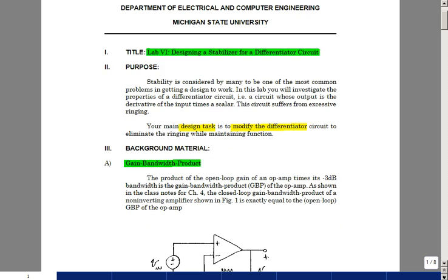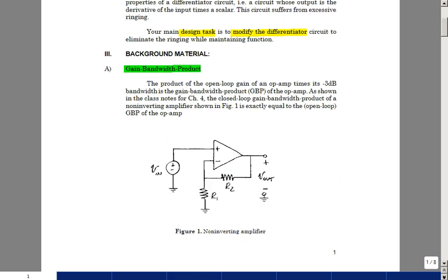Well, the techniques you looked at in class are built around using the open loop curve of an op-amp, the response of what's called the beta network. As we'll see in the next lab, it's very difficult to measure the open loop curve versus frequency. So we can play a little trick or a game, and that is to use a closed loop circuit and work some of the numbers backwards, figure out the resulting curves.